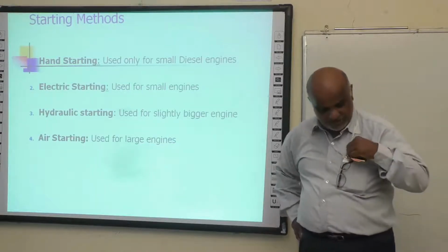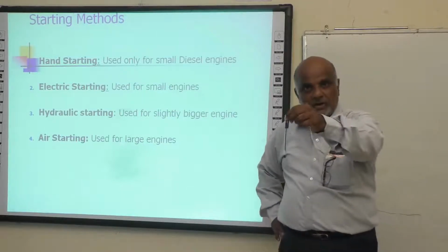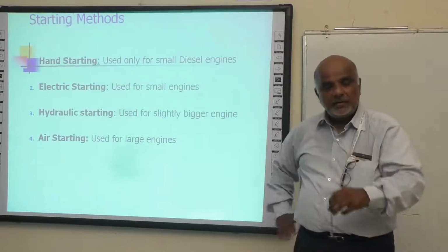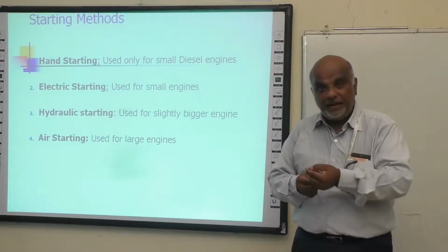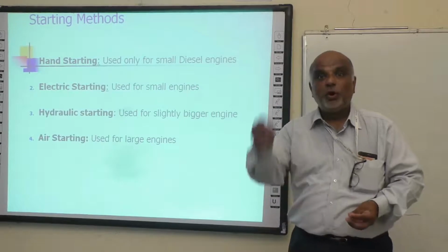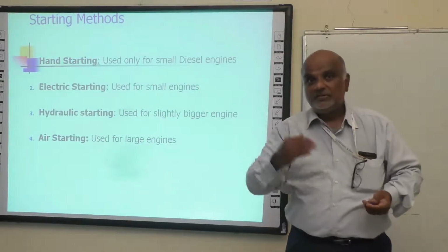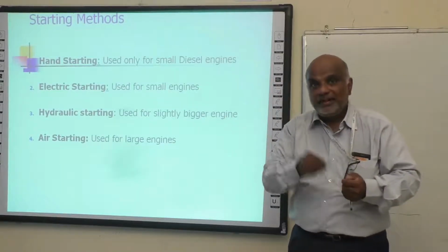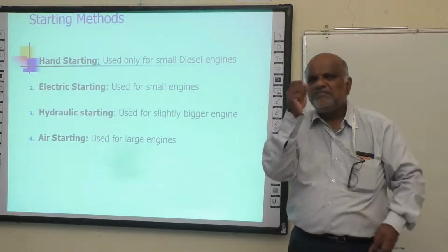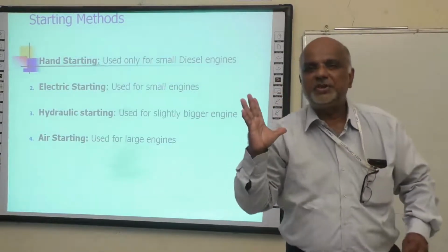I tell you, this pen, I'm not allowed to use it on a gas carrier. This pen should be made of brass, or the tips of the pen, if it touches the floor on the deck, on the main deck, where the gas is there in the big storage vessels. And if there is a small leak, microcandle power is enough to blow the entire ship.